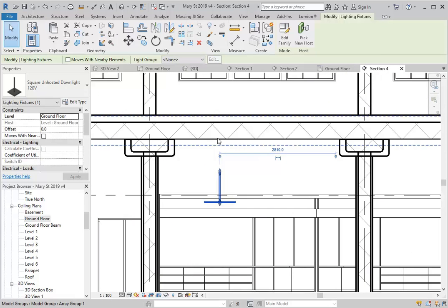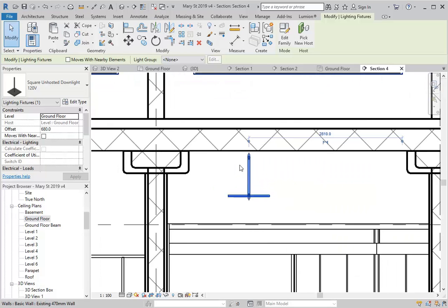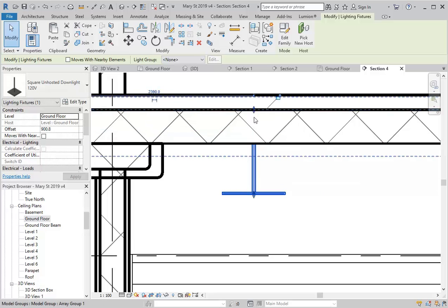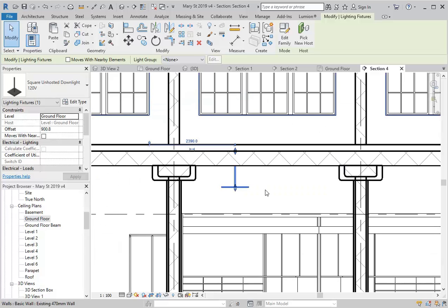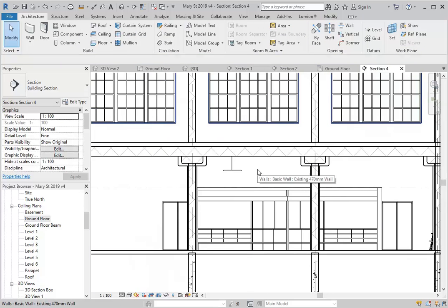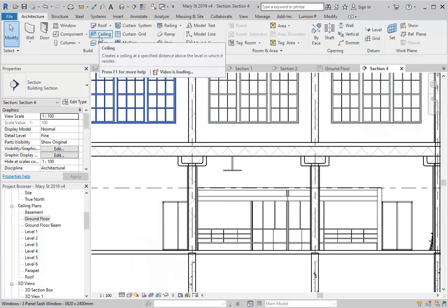It doesn't need to attach to a ceiling. And that actually makes it in some ways a lot more useful than a real ceiling light, because you can just drag it wherever you want it to go, and if there's a beam or a joist instead of the ceiling, not a problem. You can still put it there and attach it to that by dragging it. So that's what I wanted to show you, so that when you start to think about your rendering and also your design, you're not limited by the way Revit wants you to do things.